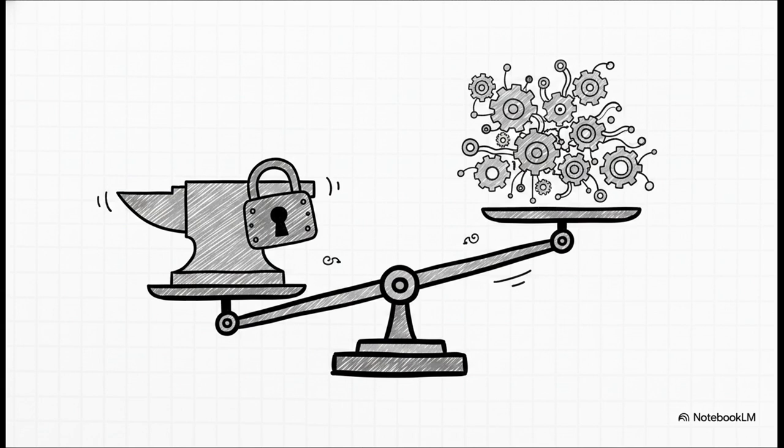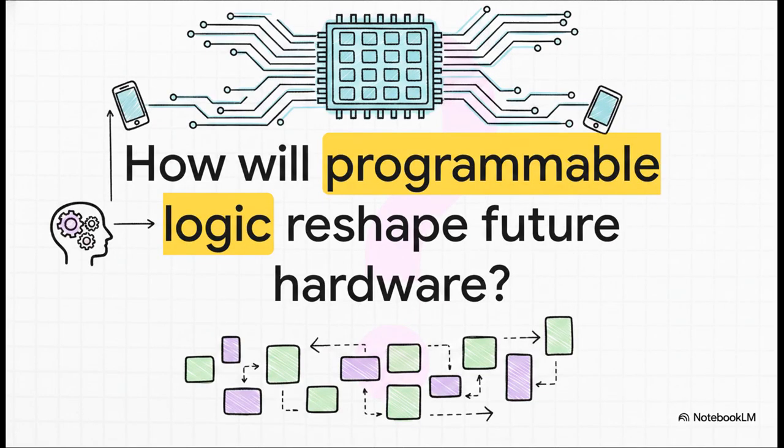And exactly how much power you get depends entirely on the architecture, whether you're working with the fixed AND constraints of a PROM, the balanced trade-offs of a PAL, or the ultimate, adaptable complexity of a fully programmable PLA. I'm going to leave you with this thought to ponder. If user-programmed PLDs offer this much incredible flexibility, how is this shift from rigid hardware to adaptable logic going to dictate the future of the smart devices we use every single day?